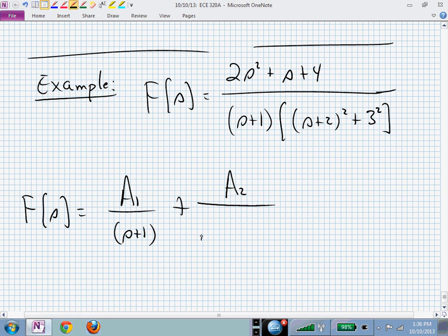So this is now going to be one of my factors with a root at minus 2 plus j3. That's in the third quadrant in the complex S-plane. And then I have a factor s plus 2 plus j3. That's the conjugate of the previous one, and it's going to be in, where did I say? Did I say the second quadrant on the first one?